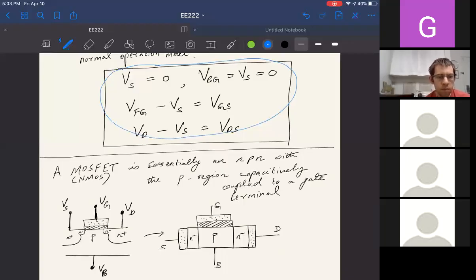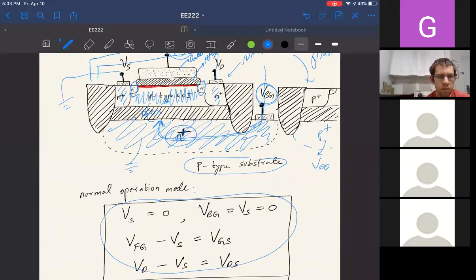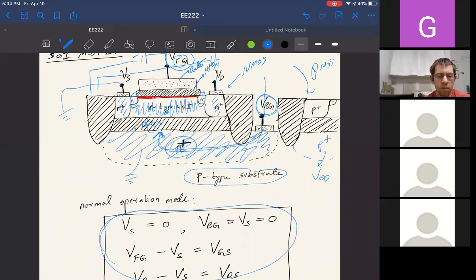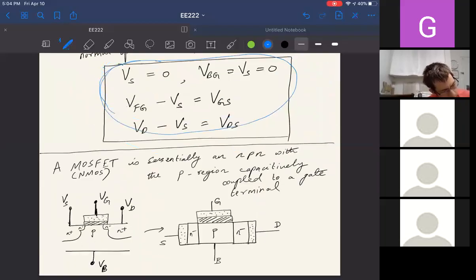By the way, the MOSFET that we are going to use is something called partially depleted, not fully depleted. The partially depleted MOS operated in this fashion works very similar to a normal bulk MOS. So the equations that describe the threshold voltage and all for this partially depleted MOS are the same as a normal bulk NMOS and PMOS. For the design equations, you can refer to any standard semiconductor book for the threshold voltage and all that.